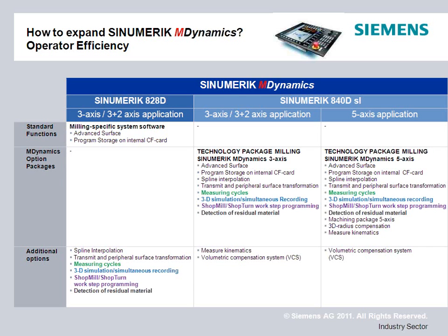We also have measuring cycles as part of this bundle. Measuring cycles would be our probing cycles in terms of locating your part. And we've developed quite a few new screens to not only define things that would be normal features like the edge of a part or just a round boss or a square boss, but we've got features where we can find partial circles and other things of that nature. We'll get to those later on since we're pretty much finishing up the introduction here.